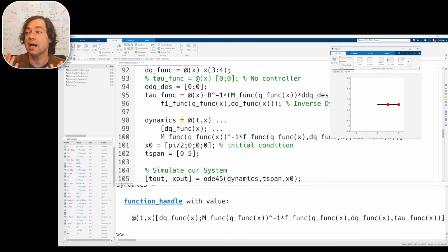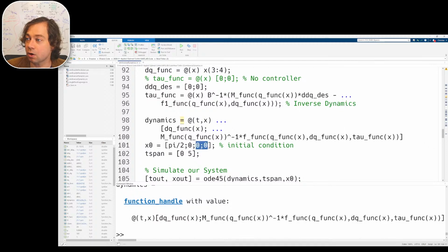Now, that's good. So when we say we want 0 acceleration under gravity, we will often call this gravity compensation. Literally, the torque is smart enough to know to get rid of the gravity. Isn't that cool? And right now it's got 0 starting acceleration, okay? But that doesn't necessarily mean 0 velocity. The only reason it's 0 velocity is we tell it that our 2 starting velocities are 0.